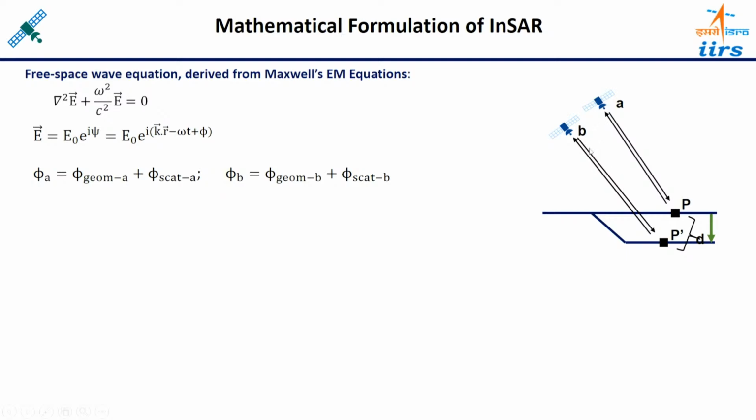Similarly, if you draw this triangle, B to P prime, P prime to P, P to B, this side is known, but this side is not known, though it can be calculated from the triangle A to B, B to P. A to B is known, A to P is known, and this angle is also known, so BP can be calculated.